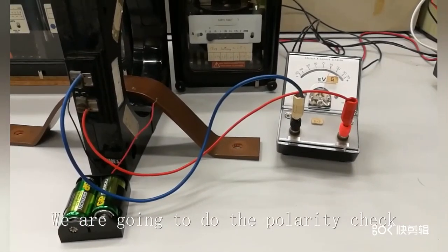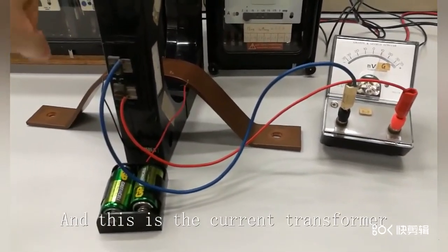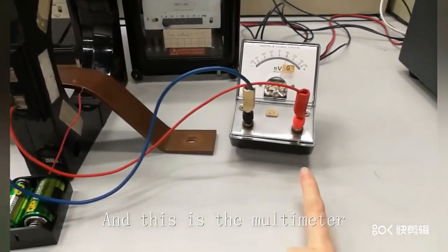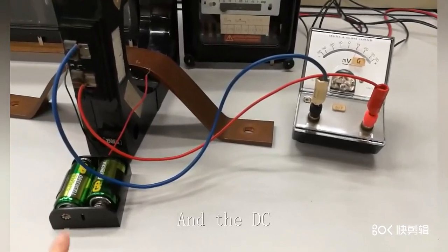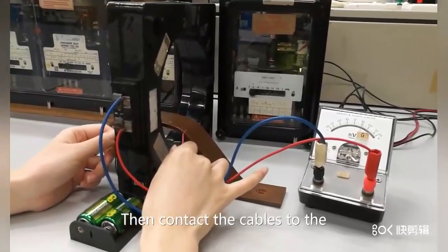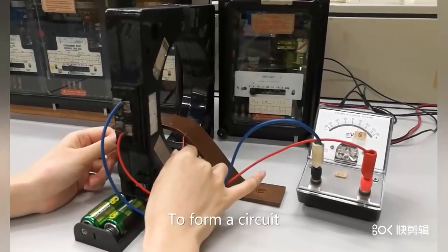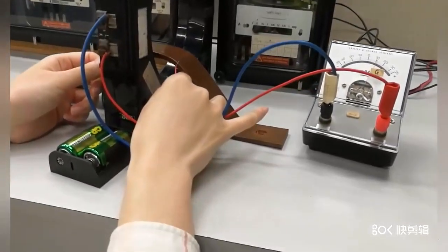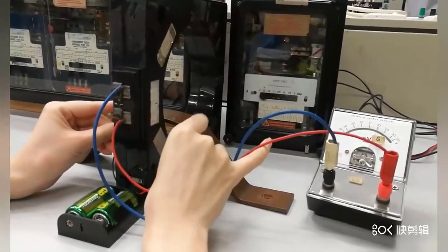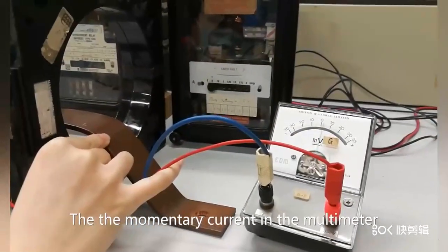We are going to do the polarity check test. Here are the current transformer, the bus bar, the multimeter and the DC supply. Then connect the cables to the bus bar to form a current circuit, and read the momentary current in the multimeter.